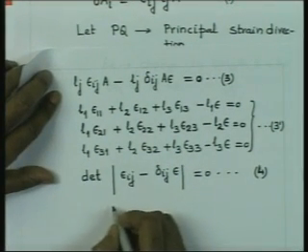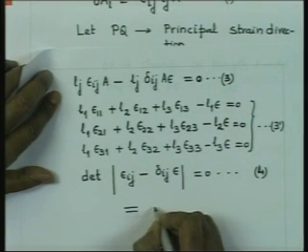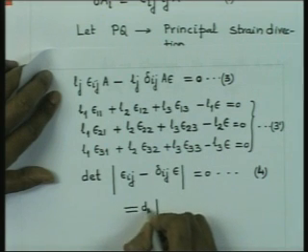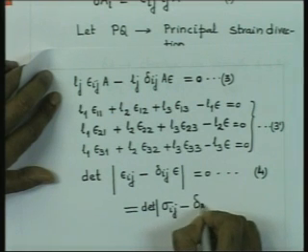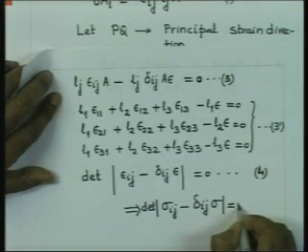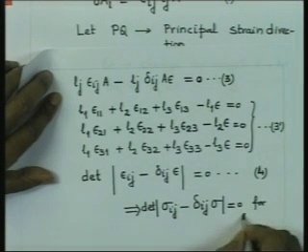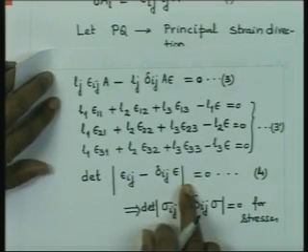and it is similar to, if you remember, in the case of stresses we had determinant of sigma I j minus delta I j sigma equal to 0 for principal stresses. So, you have got a closely parallel relationship for the principal strains. And this relation, 4, can be expanded.